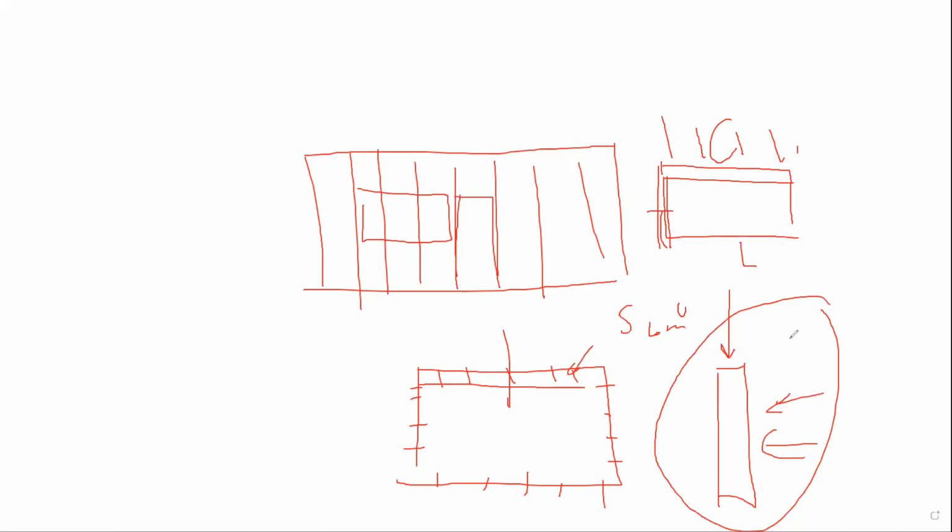So in other words, once we learn how to design the lintels, they're going to be simple. You're just going to have to realize how the load gets applied. The lintels are built-up beams. It's something that you've already done. What's going to be a little bit more complicated are the built-up columns, and they're not really complicated because we've already done some. But I'll reinforce the whole built-up column with the eccentricity, and we'll go through that.